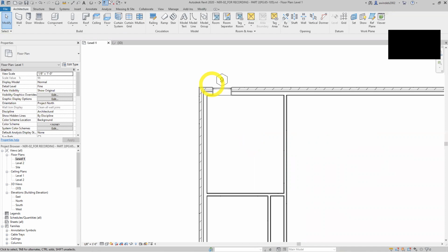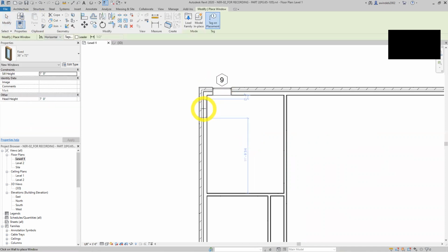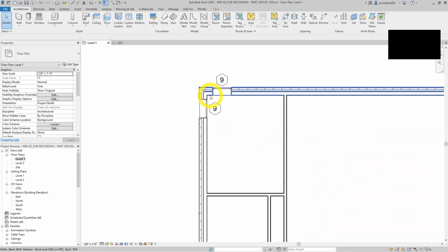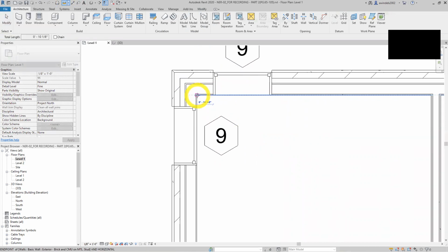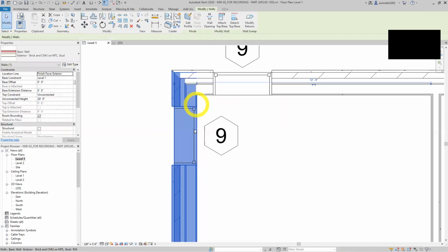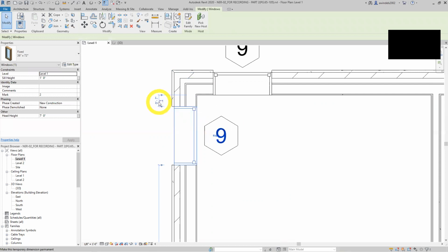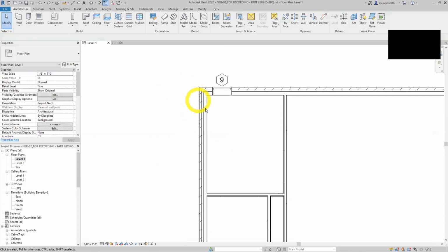Let's add some more windows. Same ones. Let's just call this one's going to be kind of similar distance. I'll put it right there. And let's check this one. Let's check the measurement actually of this. Let's make them equal. Say, what's this to here? 10 1/8 of an inch, 10 inches, 1/8. Okay, I have that option. I don't have to even slide my temporary dimension anywhere else. It's already good.